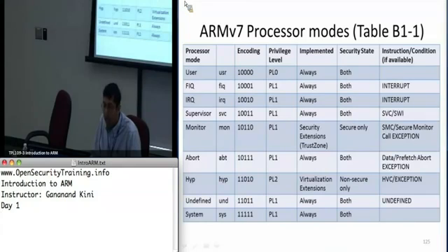If you had TrustZone on the ARM board, that would be enabled using the SMC, which is the secure monitor call instruction. So once you say SMC, it either switches to monitor mode or back from it, runs monitor code, and the monitor code can decide to run the secure code, or it can decide to switch back.